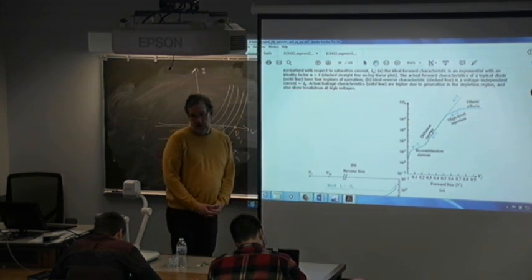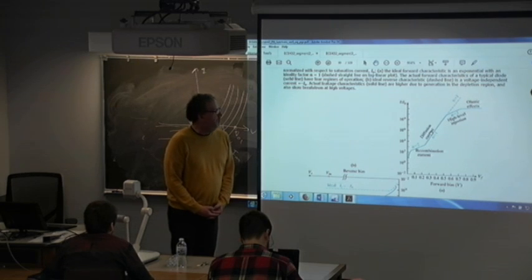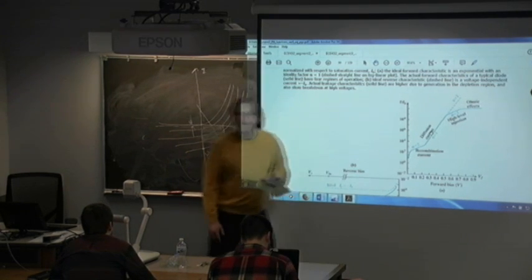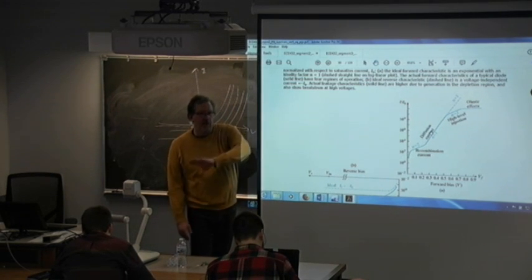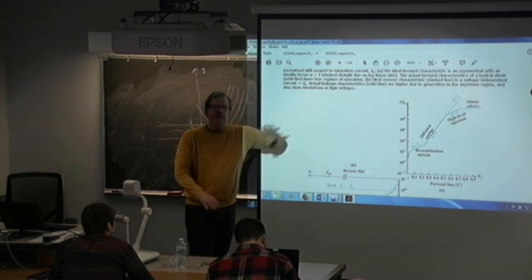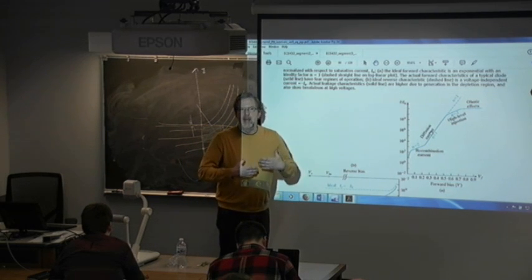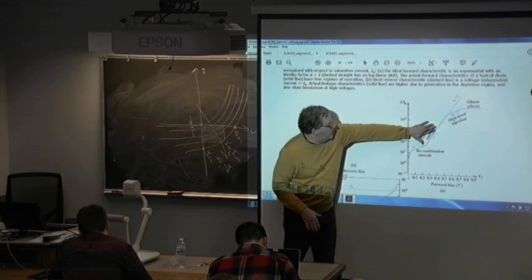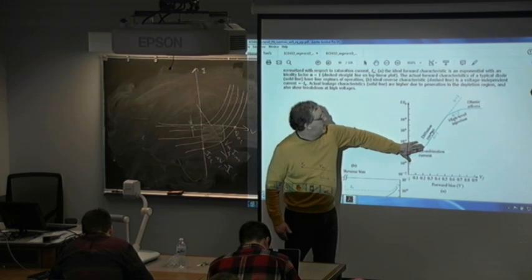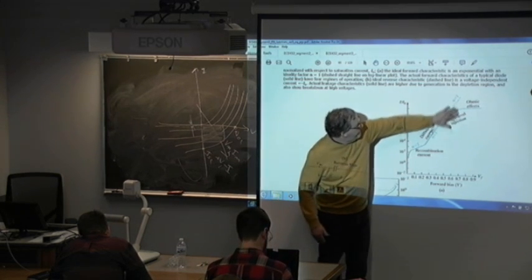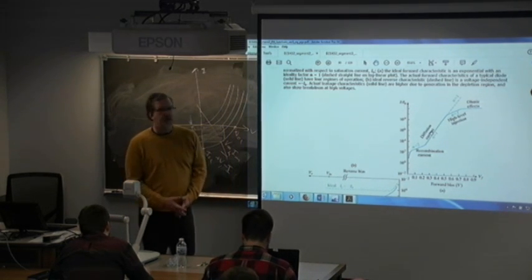So the diffusion can cause forward current as well as reverse current? Or not the drift, sorry. Drift is happening. Yeah, that's the point. The generation recombination in or near the depletion region is happening reverse and forward. It's happening all the time. It's happening everywhere, and it's happening all the time. It's just whether it's overwhelmed and masked. Here the diffusion current is so much larger that this is now overwhelmed and masked. And here it's now becoming such a large component. But normally it's hidden in the noise.